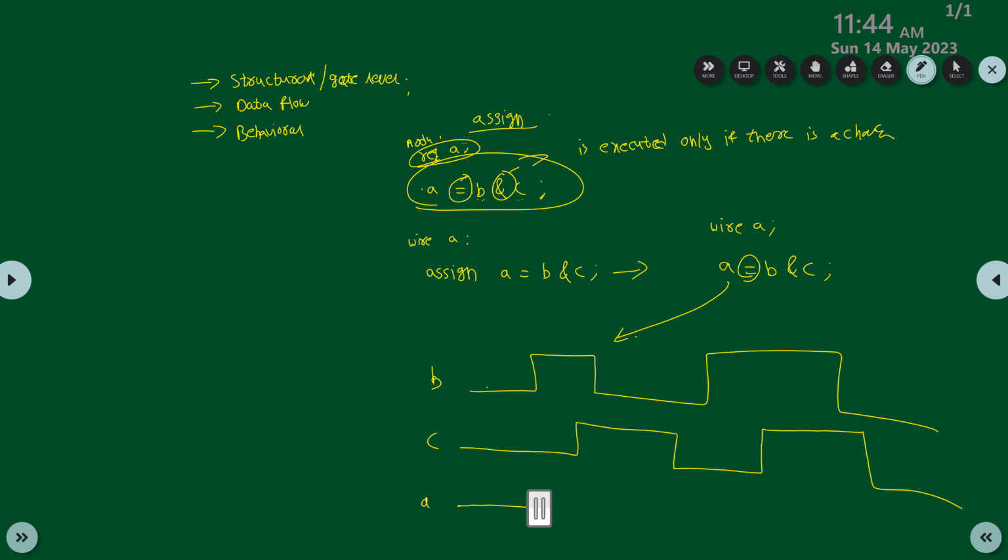From this point, you see the input is changed from 0 to 1. Let's say A is starting from 0 here. Both of the inputs are becoming 1, so it will become 1. But at this point, both are maintaining the same value, so this command will not execute again. As you declared it as a wire, it will not retain its previous value for a long time. After that, it is going to an unknown state.